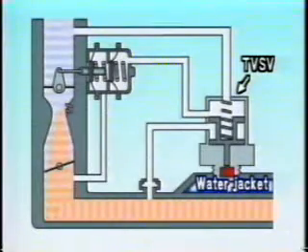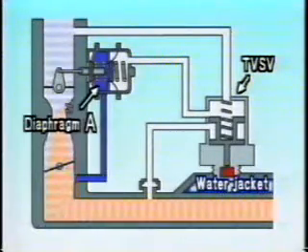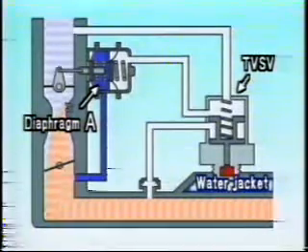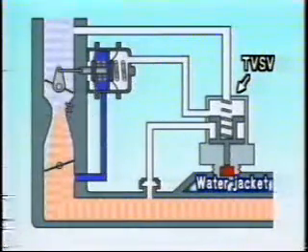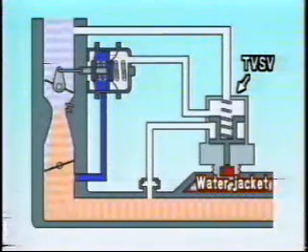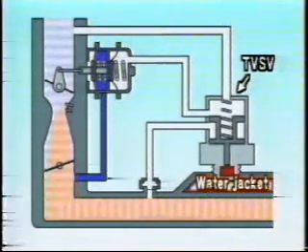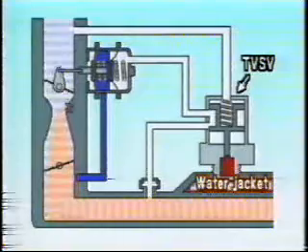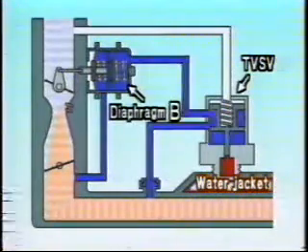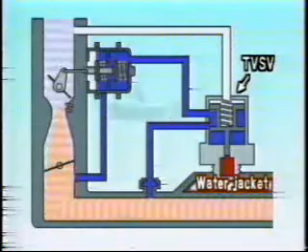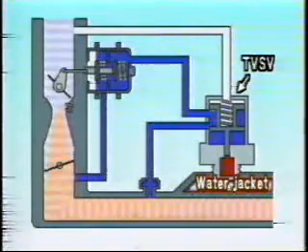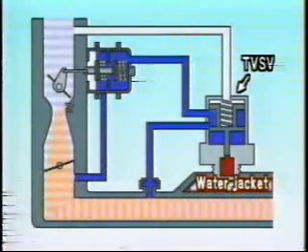When the engine is started, the low intake manifold pressure causes diaphragm A to slightly open the choke valve. Once the engine warms up and the coolant temperature rises to normal operating temperature, the TVSV opens, and the vacuum from the intake manifold causes the choke opener diaphragm B to open. After this, the choke valve is operated by the auto choke mechanism.